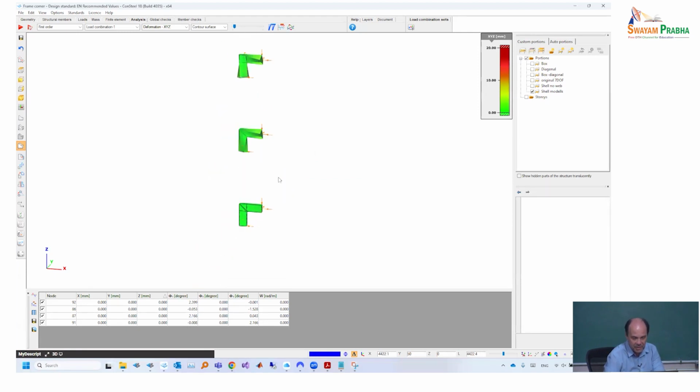So what we did in Consteel is that, of course, we are using beam elements, and it is possible in Consteel to make models with complex modelizations. It's possible to use beam elements, and for the corner use shell elements. We have constraints to consider the connected elements, including also the warping deformation. So everything is possible to do nicely, but it is slow and time-consuming to model a big structure like that.